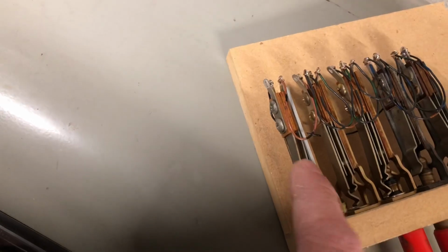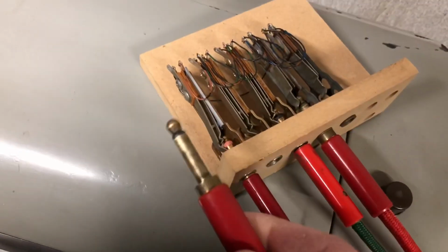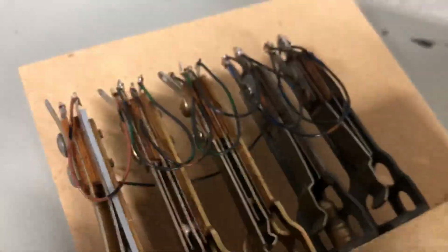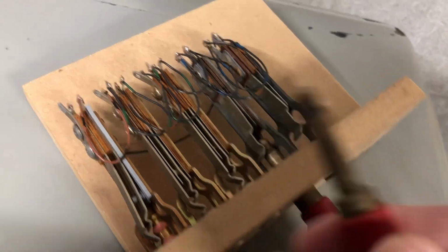The input doesn't have the switch contacts. And then these two are for this style jack here, whereas this is that style. So these have tip, ring and sleeve. This just has tip and sleeve. These are great for shocking yourself, because on a teletype loop, that means there's going to be voltage there. So I just have to be careful. Anyway, let me plug these in.